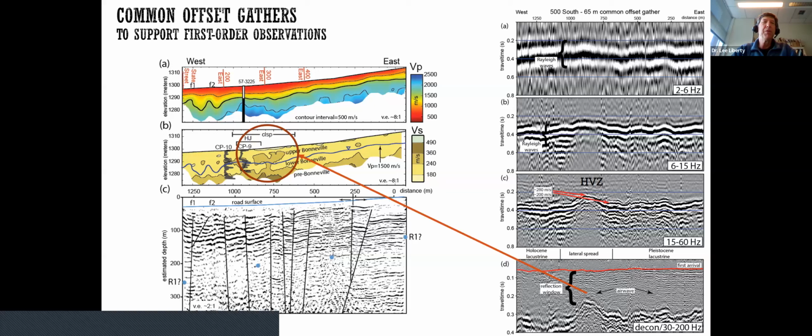A rule of thumb with Rayleigh wave inversions is you're able to estimate shear wave velocities to about a half or a third of a full wavelength. So that gave us the confidence that we could interpret down to 30 meters. VS30 is a standard that geotechnical engineers or earthquake engineers use for estimating site response. And so we use that as a metric that we want to try to image down at least 30 meters with our Rayleigh waves, to measure estimates of shear wave velocities.